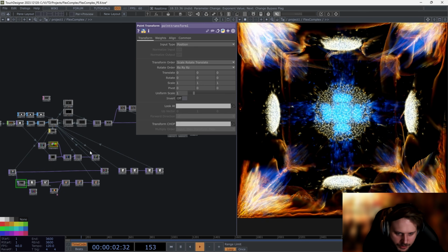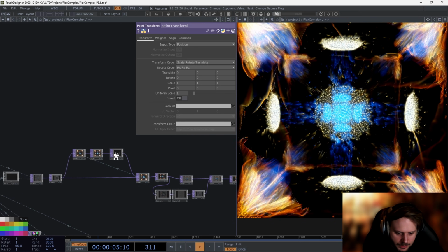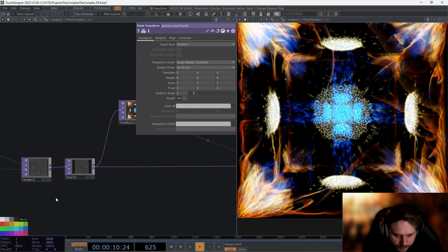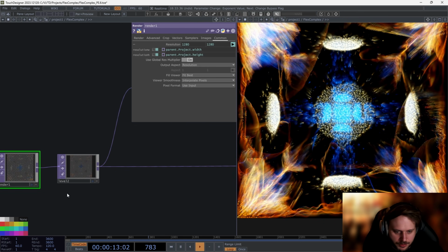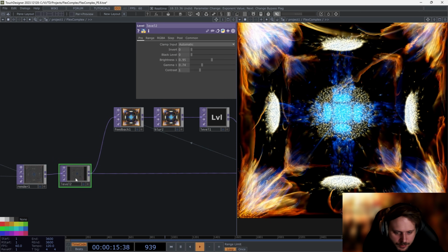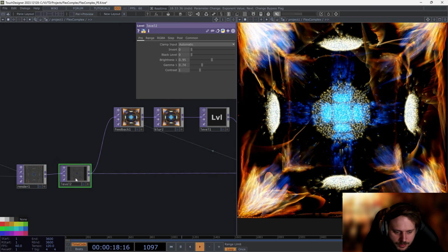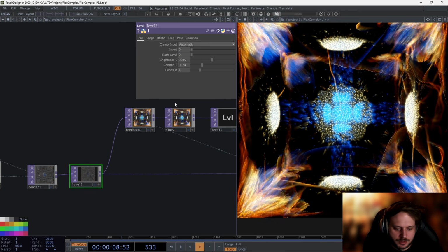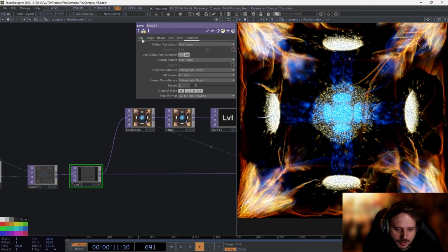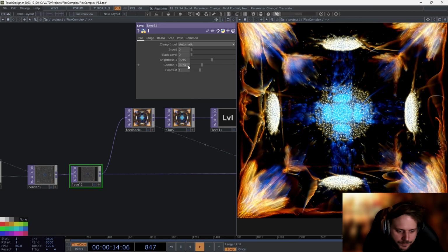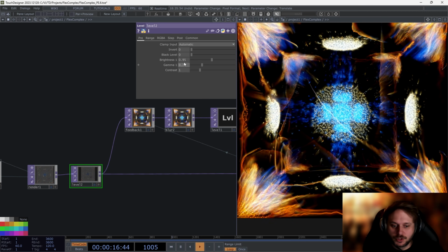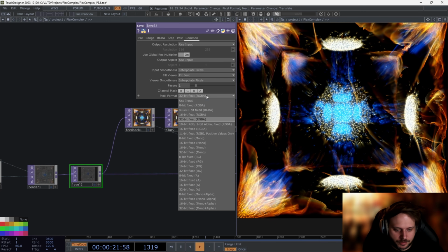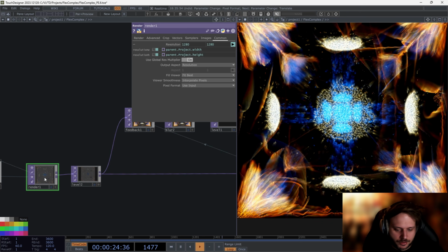That's the Nvidia Flex setup, and for the post effects, there's also some little tricks here. I mean, not much. First of all, obviously we render it to a render top. Then I put down a level top to make it 32-bit float. And the reason that I'm doing a level top after the render and setting this level top to 32-bit float, I mean, okay, first of all, I'm changing the brightness and the gamma. That's one thing. But even if I wasn't changing the brightness and the gamma, I would just put this level top down and set it to 32-bit float here, as opposed to setting it on the render top.